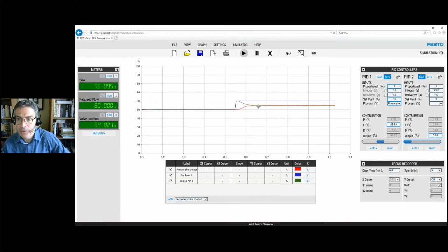The red curve does not reach the set point because we are in proportional only mode. So this is the constant error, the offset I was talking to you about earlier. The red curve did not rise high enough. We would like it to rise quickly and then oscillate at least once to get a proper response.